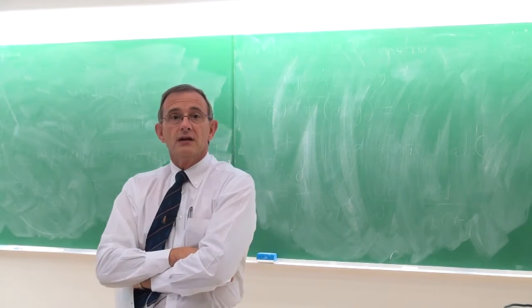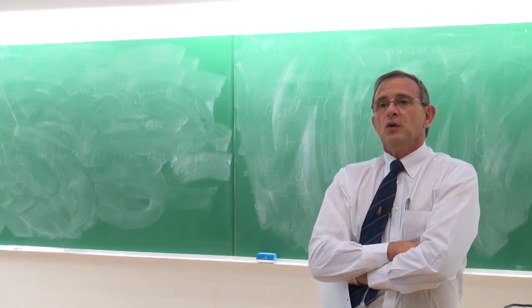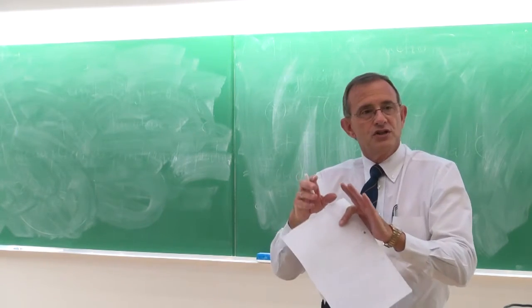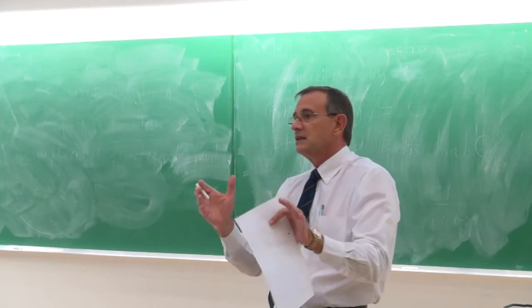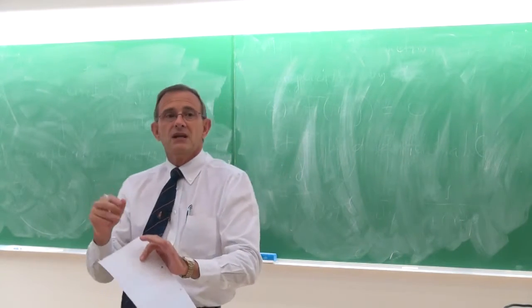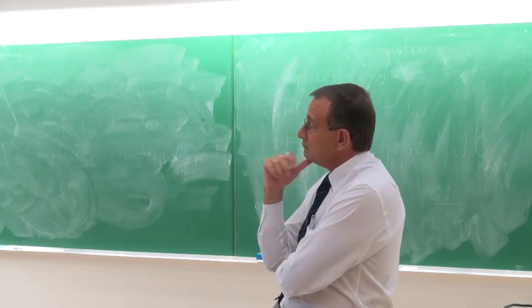However, the one thing that is always very important to remember is that with the lumped system approach, we get a temperature. And that temperature for the body is the temperature everywhere, on the surface and the center, etc. So it is, in many cases, maybe a first good order approximation.